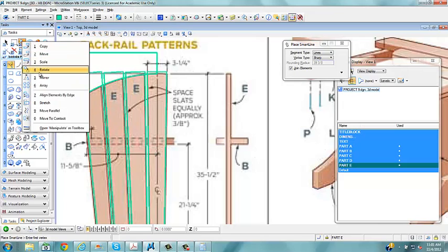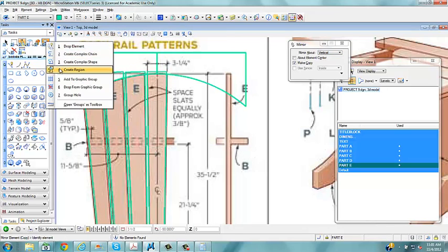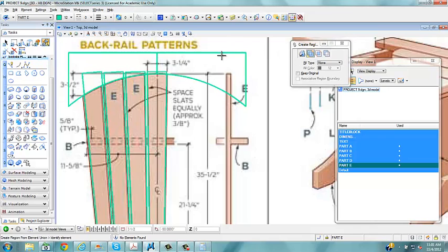Now I want to mirror that to the other side so that we end up with this little bit of a curve on the other side of this one. We'll boolean those two together in 2D. Now, what we're going to do is find the Boolean difference between, and I want to keep the, between this, this, this, and this.